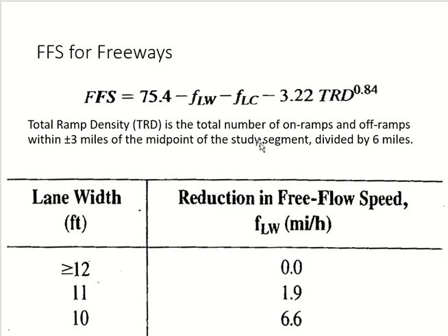Okay. Now you are designing. You are in the design office, you are designing. Somebody asks you about the lane width. So what would you take? Easy way out is what? Why 12? Because the factor becomes 0. Why does the factor become 0? Because it is standard. 12 feet is the standard value. You take the standard values, you don't need the adjustment factors, right?